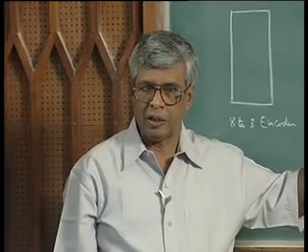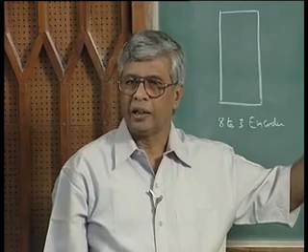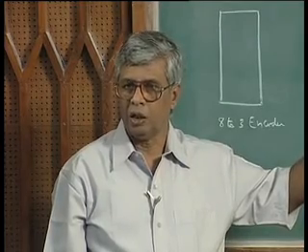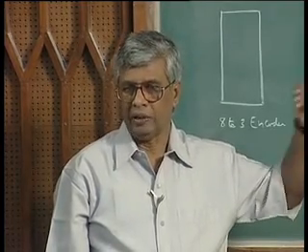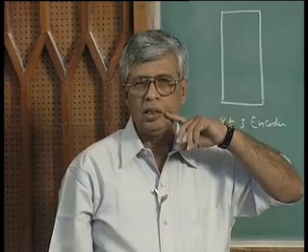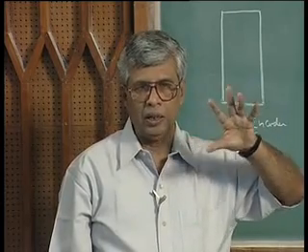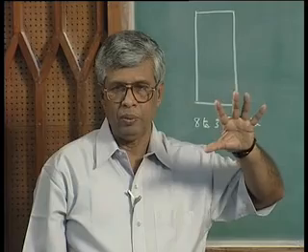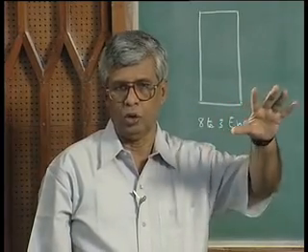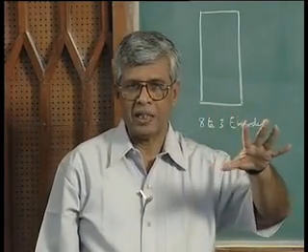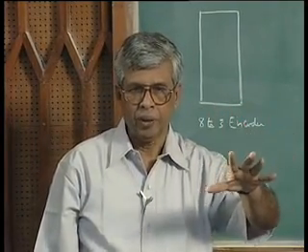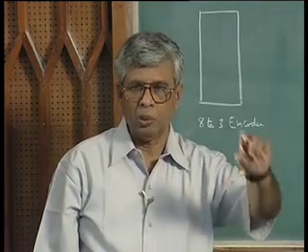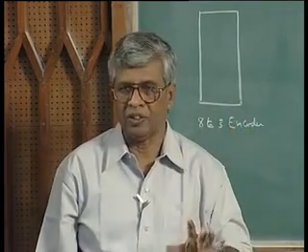By combination of these 3 bits, we can determine which is the active input, all others are inactive at that given time. So, this is the process of encoding. Encoding reduces the number of inputs required from 8 to 3, for example, or 16 to 4. So, compressing the data from different possibilities into a smaller number of bits. That is the process of encoding.